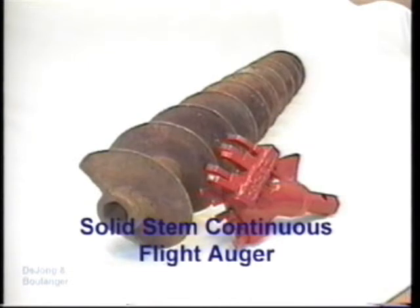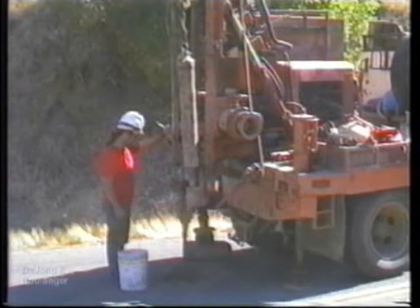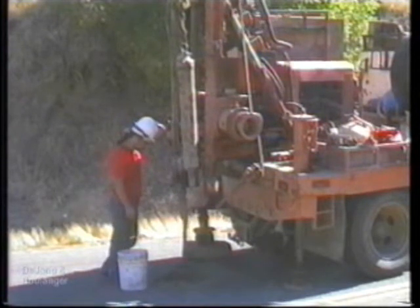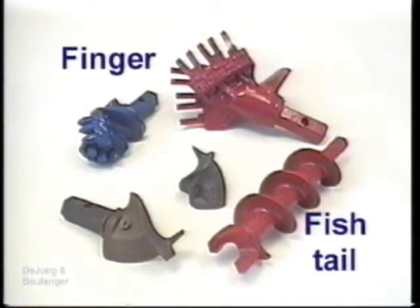The solid stem continuous flight auger method is the simplest drilling system with only 2 basic components, the drill bit and the auger flights. The drill bit is located at the tip of the drilling stem, with the stem consisting of individual auger flights connected together. When rotating, the drill bit cuts and loosens the soil, enabling the flights to lift the soil out of the hole. Variations of the 2 most common types of bits, the finger and fishtail, are pictured here.